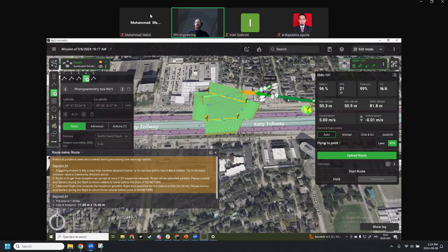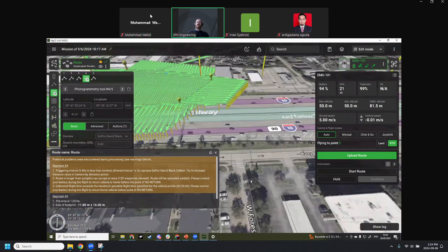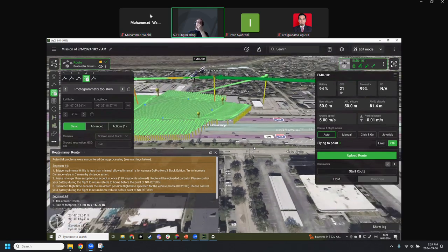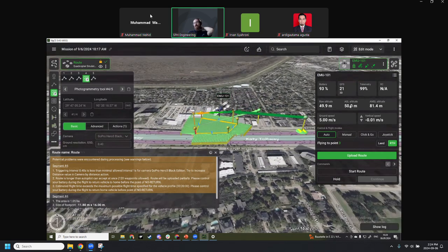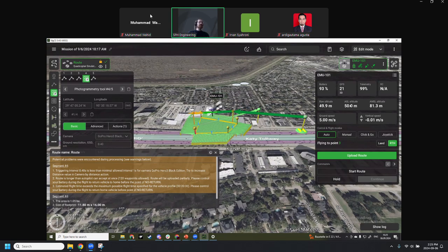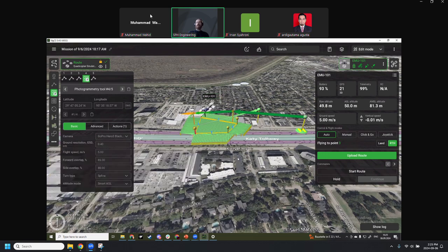various altitudes. So raw, this is the altitude from takeoff point, because all drones mostly use the barometer to understand its relative elevation. And the AGL altitude is the above ground altitude calculated from the elevation data in UGCS. So the AGL altitude value may be different in different flight apps because they use different data sets for elevation.